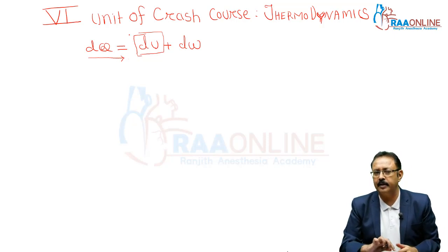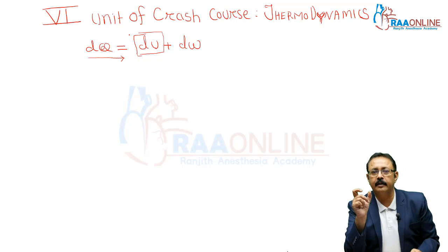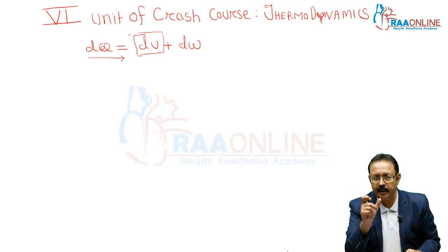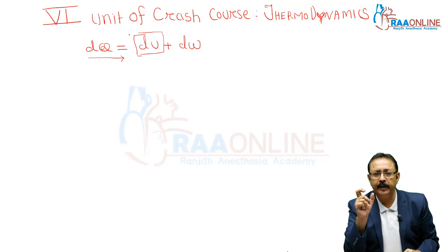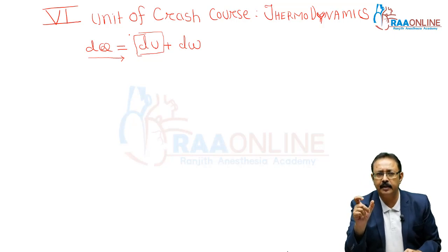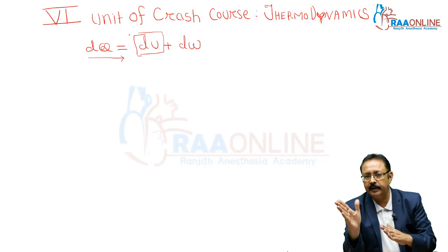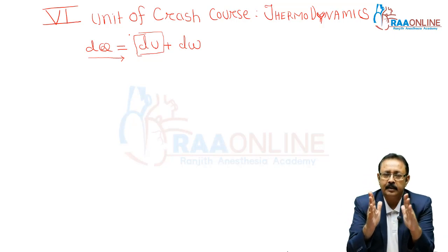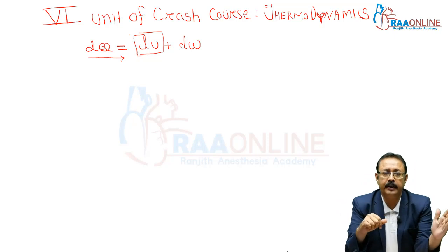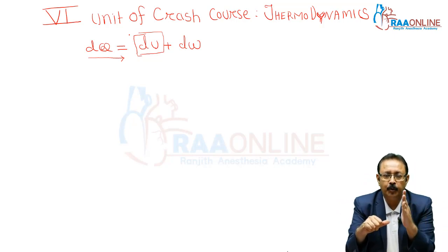The dU sign convention is simple. If internal energy is increasing, the sign of dU should be positive. If internal energy is decreasing, the sign should be negative. Clear to you? It is very simple. Left to right, dQ and dW both are positive, meaning the system is absorbing heat energy and doing work.